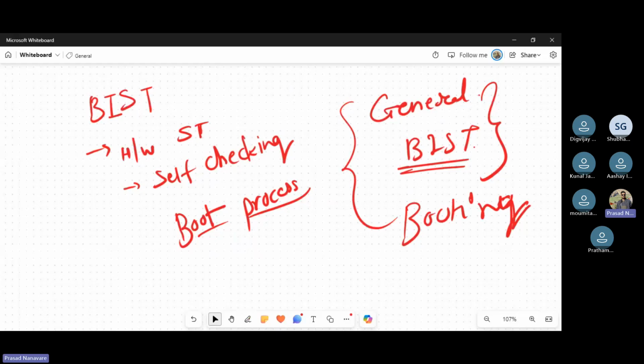Next comes test hooks and debug interfaces. Debug interfaces are for debugging purposes, and test hooks. These are self-explanatory sort of. The debug headers include extra test pin headers or connections for serial, JTAG, serial wire debug or other debugging protocols.